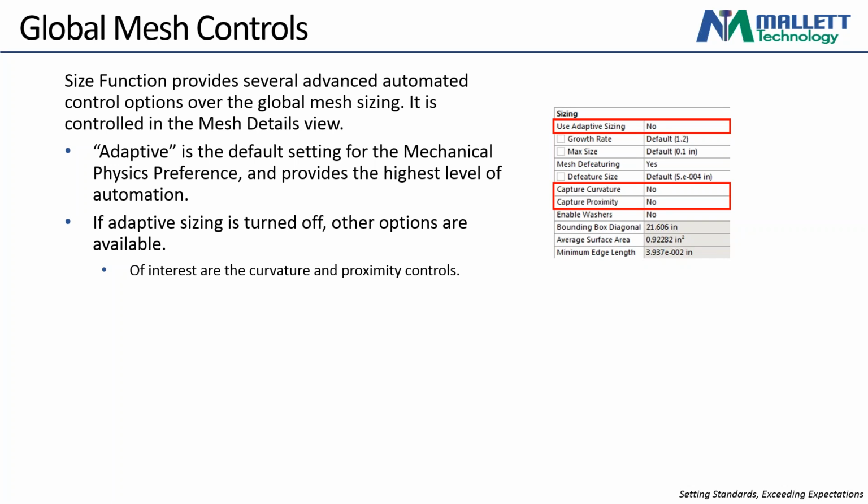The most automated and the one with the least amount of control is the adaptive method. Honestly, from my perspective, it's not recommended. When you're running an FEA analysis, the user and the analyst running that job should have full control of every feature. There are times where adaptive is probably acceptable, but generally, even if it is, I will switch it off and then manually apply my mesh control so I know exactly what's happening, exactly what the sizing is, and I'm not just specifying finer or coarser.